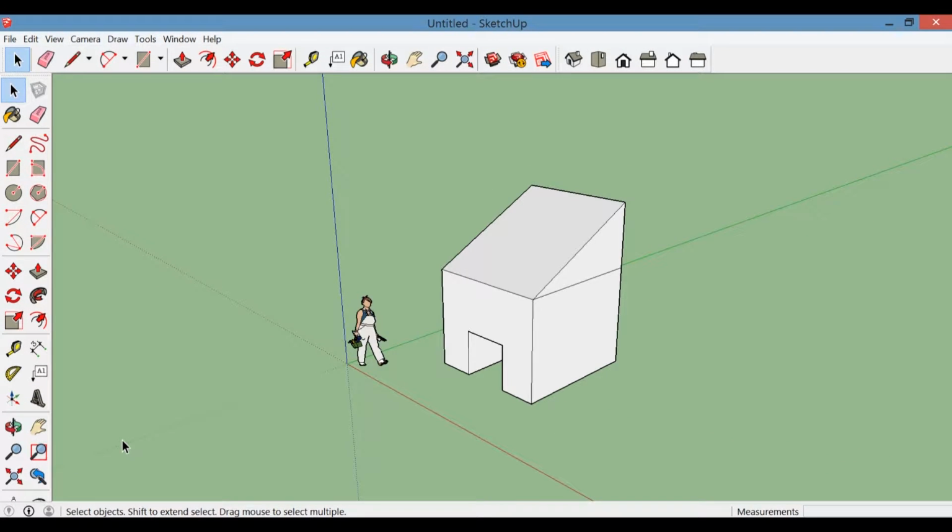Now, in terms of getting around your model, which in my case is this sketchy house shed thing that I've drawn, most CAD programs will give you 4 options: pan, zoom, orbit, and directional views. All of these will change how you see your model, but they won't actually move your model itself. Instead, you can think of it as them moving your position relative to the model. So maybe it's you walking around the shed or you jumping up and down relative to the shed.